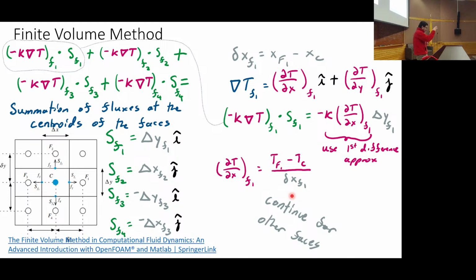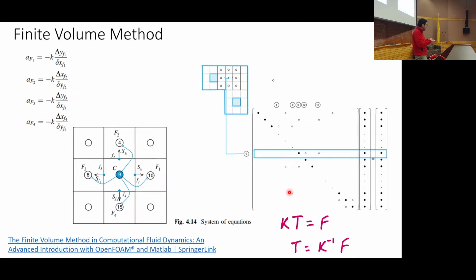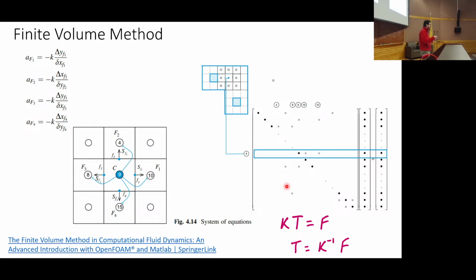Essentially you had to do some finite difference here, as you see, but that's it. You've got the delta t, the minus k times it, and you solve for these fluxes on all four sides, and you set up your k matrix and you invert it. That's it. So this is a very simple technique, and it turns out it's very powerful and it conserves volume. Imagine that, right? That's kind of at its crux.